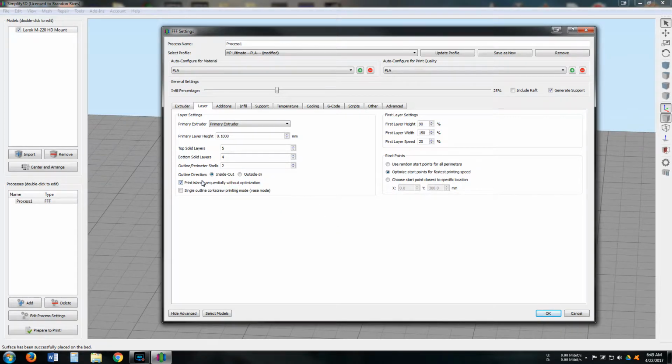Haven't really used that one. I have used this one. Basically, vase mode only prints the 1 layer all the way on the outside, even if it's a full model. So if you want a cylinder, you can get a solid piece in an STL file, and then you can check this mode, and it will only print the outside layer and the bottom.